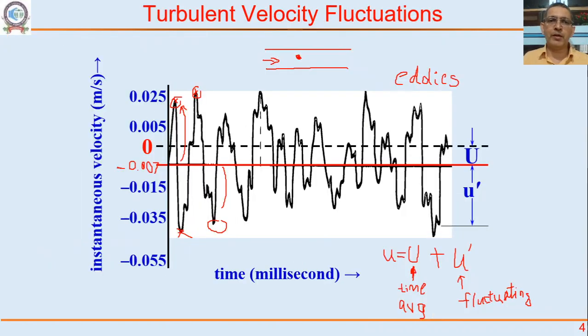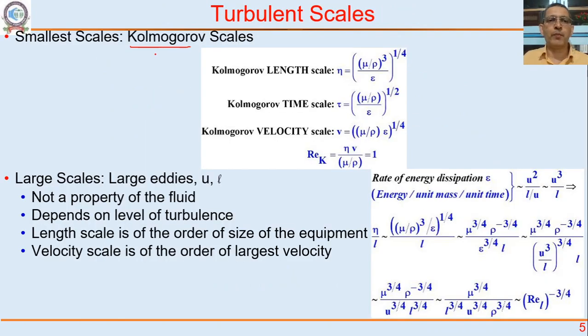Whenever you see a turbulent flow, he proposed that the turbulence is generated because we are dissipating energy, generating momentum arising out of delta P, or gravity, or maybe agitation. We are generating momentum by dissipating some power. Power could be in the form of a pump, pressure drop multiplied by volumetric flow rate, or the agitator motor power.